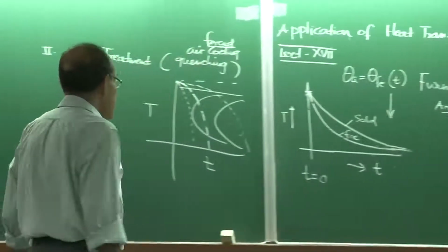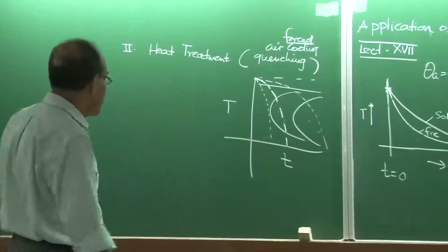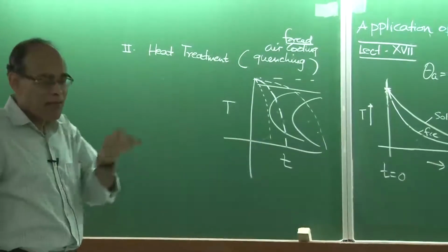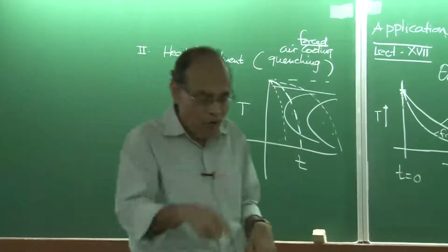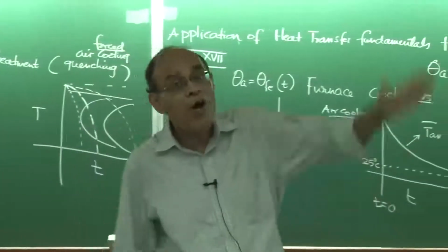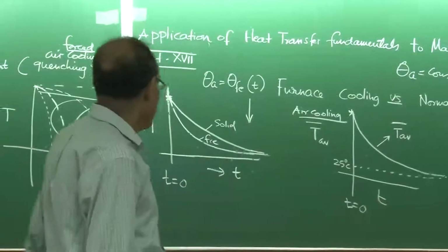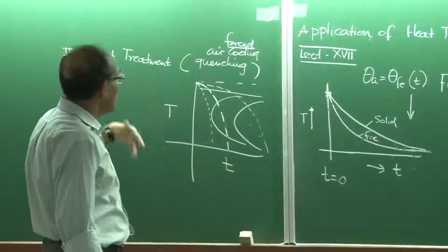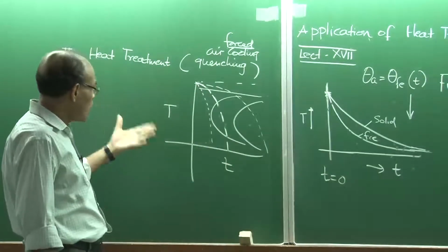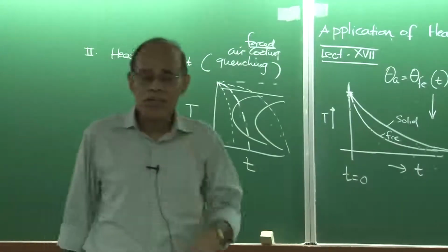So you can only look at the cross section of the wire to see what is really happening. There is a theta symmetry, because it is a complete round wire, and the wire is very long, so an infinitely long cylinder concept holds good, and therefore you can study the heat transfer related issues by considering only the radial conduction of heat.